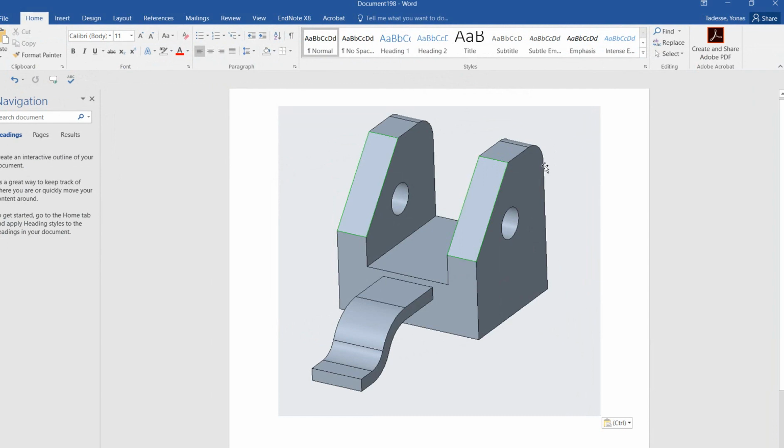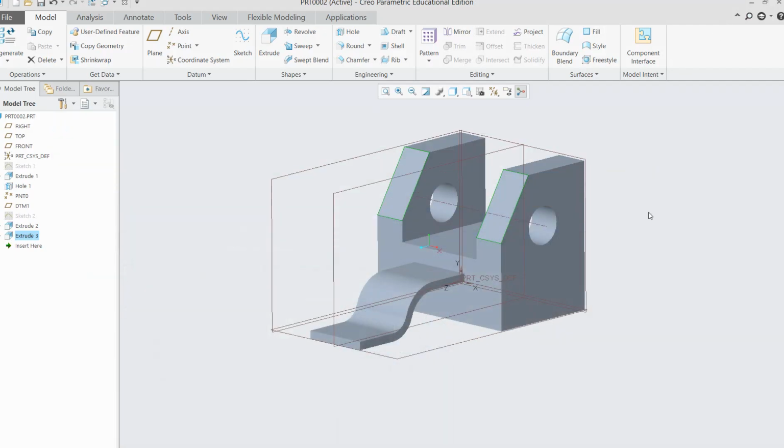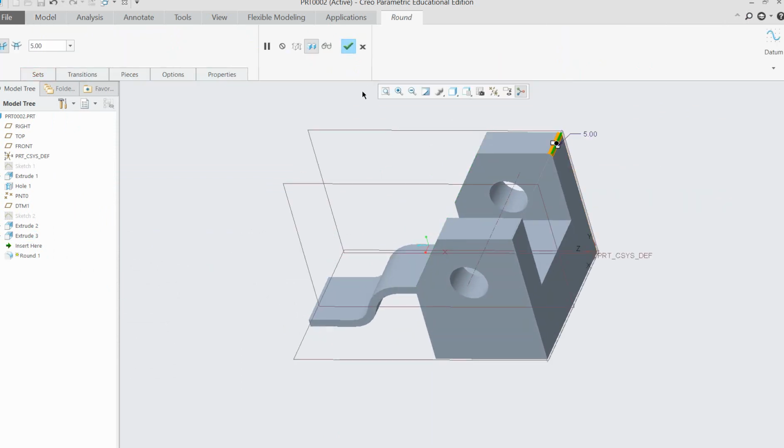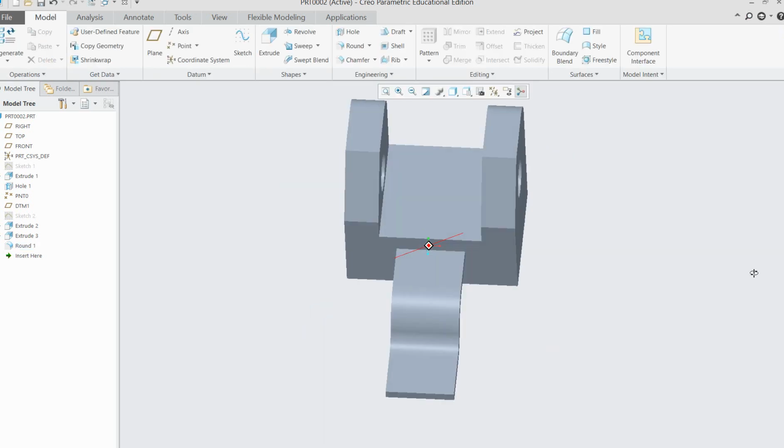I have one fillet here. So that is, rotate this guy, round. You can select multiple rounds, and then this 5 is smaller, so I make 10. Still smaller, so I make 20. Oh no, I need more, 30. Okay, that looks good, and then I will do the same. You can do all at once. That's it. So this completes the modeling.